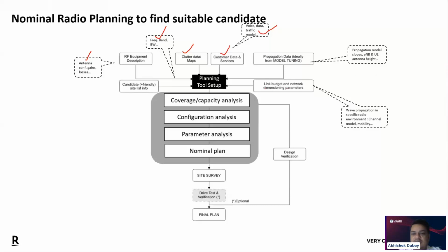And the last but not the least is the link budget. I already explained this. The link budget you can calculate from the MAPL, the maximum allowed path loss. This maximum allowed path loss is the difference between your total transmit power and what you have received. In other words, it is EIRP, effective isotropic radiated power, minus the received power. The difference of this is your MAPL, and through MAPL you can calculate the link budget.